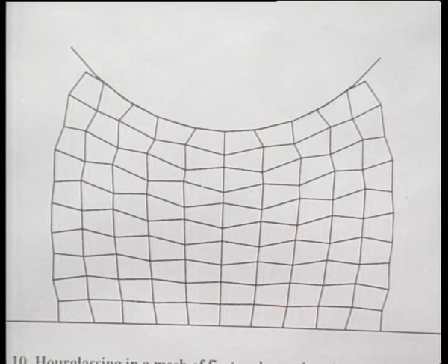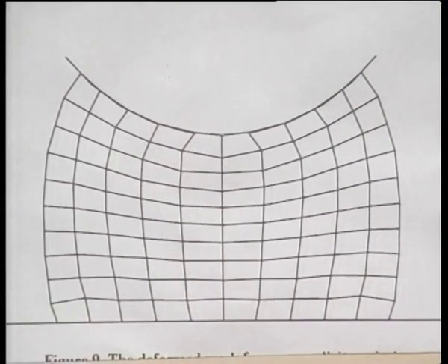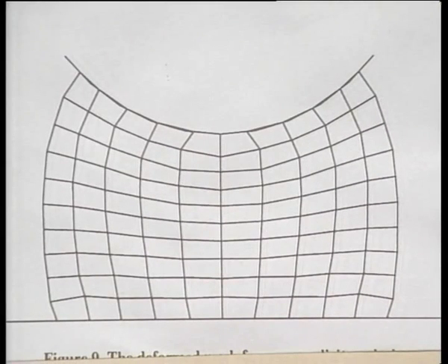Now let us look at a proper result in the next chart. Now that is the actually proper result. The mesh is smoother with a proper integration, and hence we also land up in trouble by using reduced integration points. So in other words, there are two issues here.